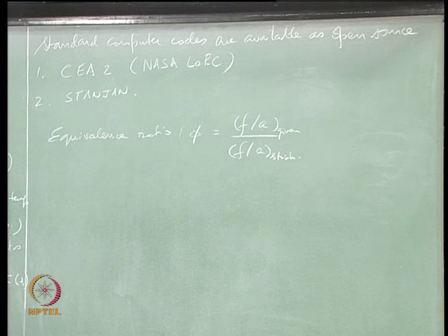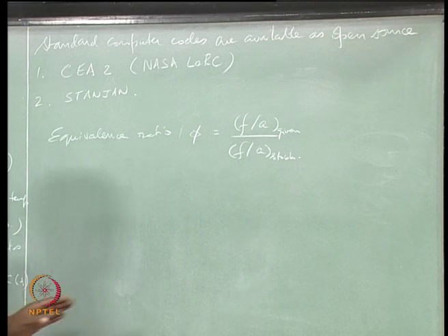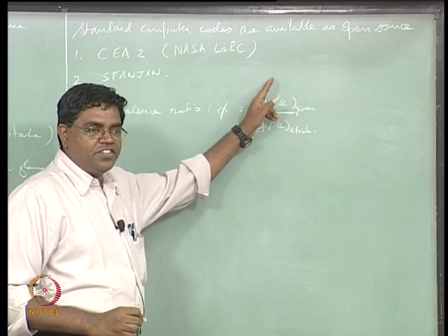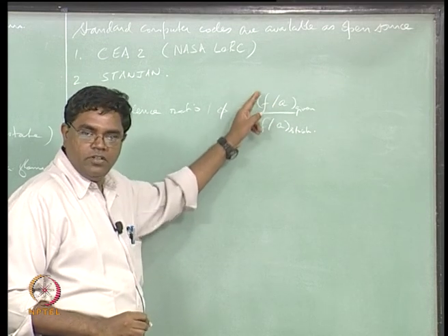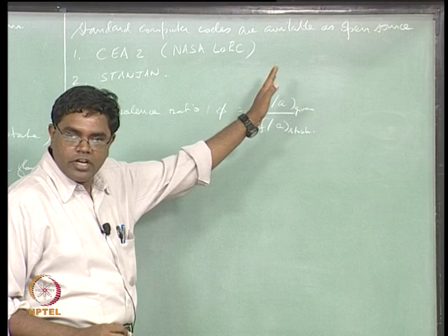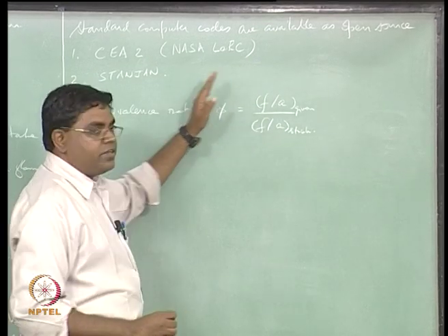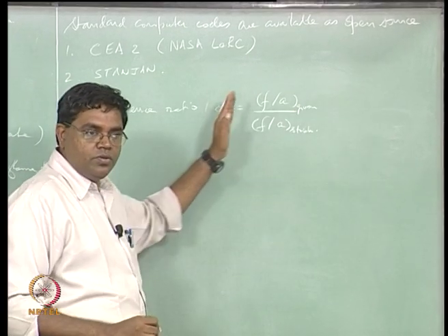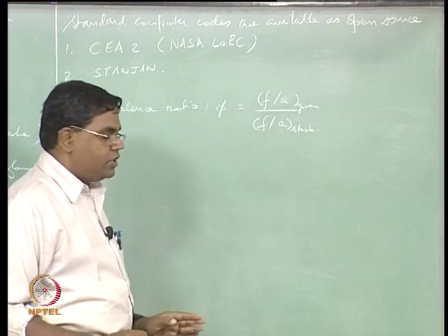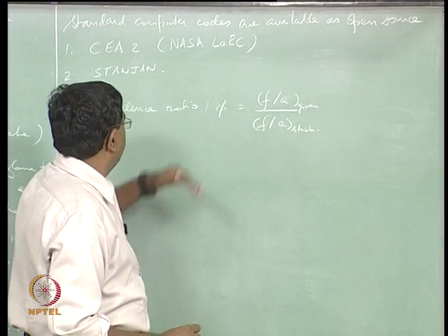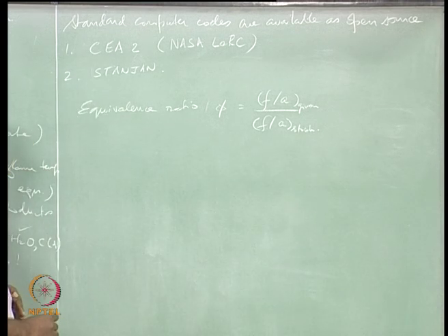In other words, you don't really worry about exactly what the stoichiometric fuel air ratio is. And of course you can also think about what if air is not the oxidizer. Not all of air is oxidizer, only the oxygen part of it is typically the oxidizer. The nitrogen is like an inert. Doesn't matter, you can look at a fuel oxidizer ratio or fuel air ratio.